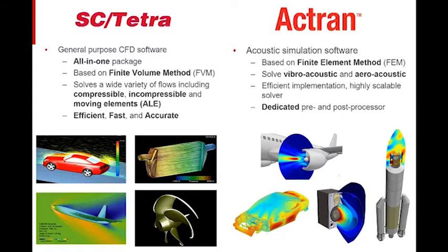Now I'm going to talk about the challenges for aeroacoustic simulation. As you can see from the image here, this shows the static pressure acting on the surface of a car traveling at about 100 kilometers per hour. The dynamic pressure from the fluid flow is about 500 pascals. To compare that with the acoustic pressure at a noisy intersection of a big city, it generates about 75 decibels of noise, and that translates to an acoustic pressure of about 0.1 pascals. So the scale difference between these two is significant. Whereas in CFD, we have only one pressure value, which combines these two pressures. So there you can see the challenge in simulating this aeroacoustic problem in CFD.